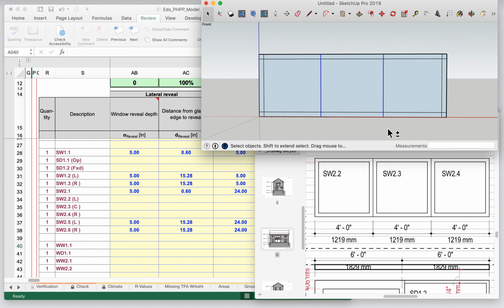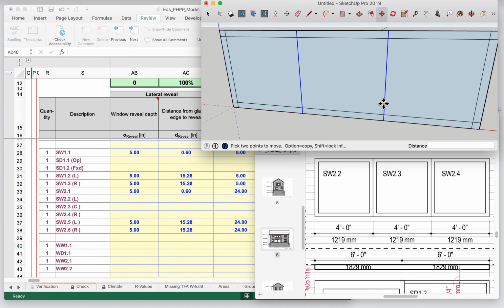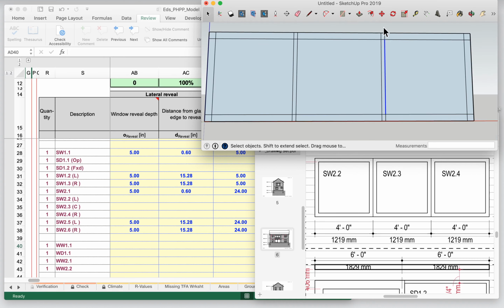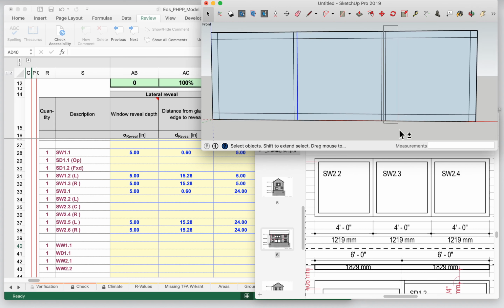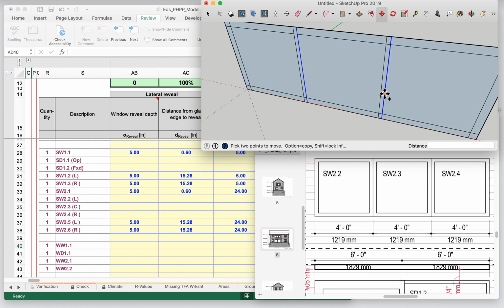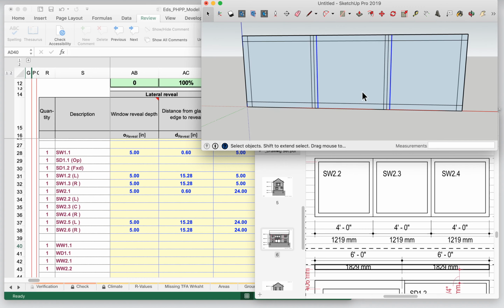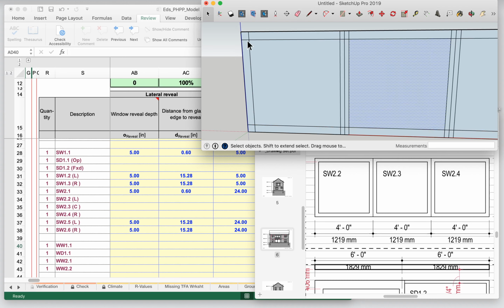All right, and we are also going to want to draw in our mullions here. So I'll come over and grab these guys, move them over 51 millimeters, and I'll do the same thing the other direction. Try and select all these. Oops. Try and select the right. Oh boy, now I've done it. Trying to select the right ones here. There we go. And I'll pull these guys over 51 millimeters, and there we go. So we've got our 3 panes of glass, and then we've got all of our frame elements there.